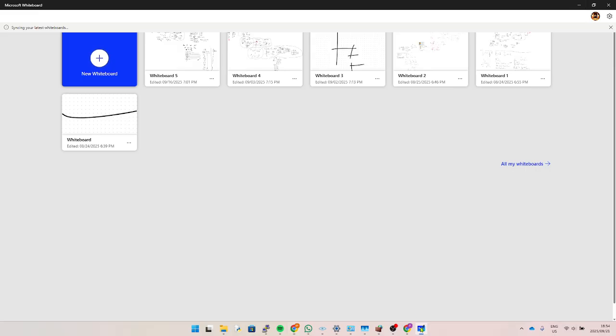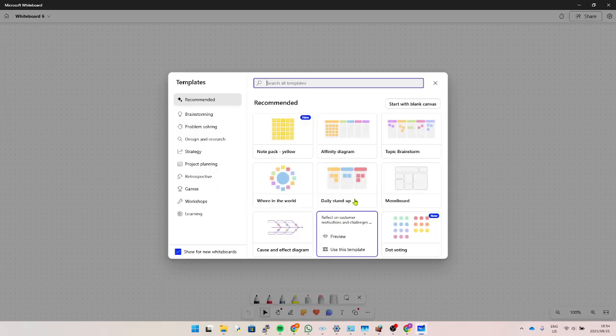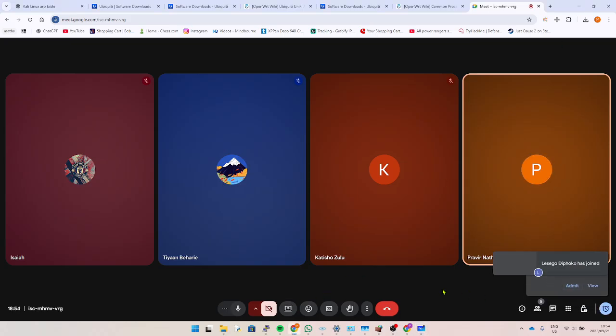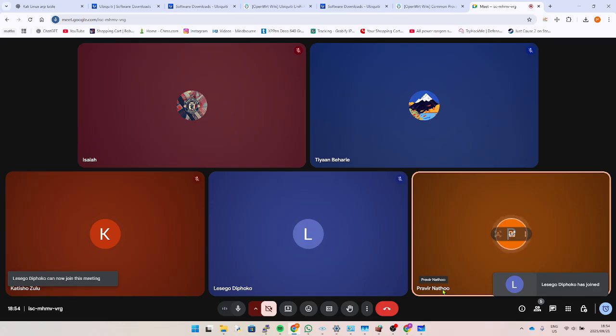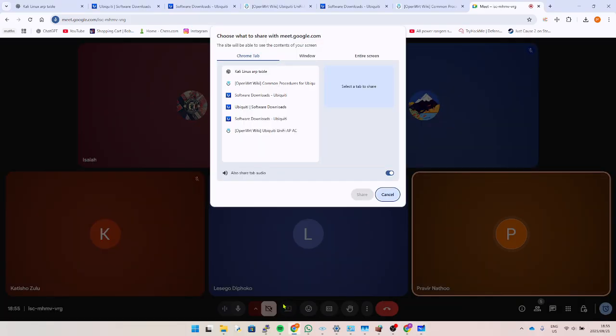And mainly we also do something called serial.begin. The function of serial.begin is to initialize the communication between your computer and the Arduino board, specifically using serial. Now, we won't go into depth about the different communications like USB, serial, VGA. We won't go into depth, but serial is the only communication we will be using. Okay, that's what void setup does.